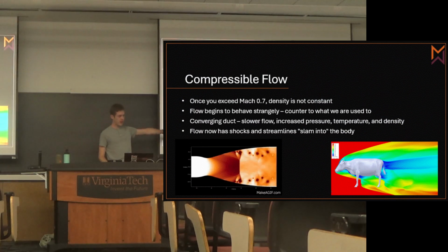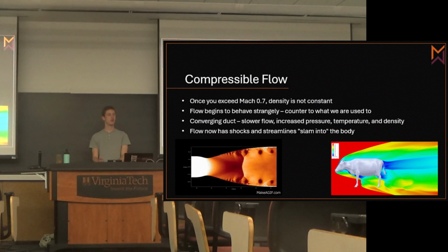And then I like to imagine when you go to compressible flow, especially once you go past Mach 1, that instead of a bunch of runners, you're a bunch of people on a highway with blindfolds trying to go as fast as they can. If someone stops ahead of you, you're not going to stop until you slam into the back of them, and that's the only way you're going to find out about it. How fast am I willing to go on a highway when I'm blindfolded? If I go down to 2 lanes with a bunch of people on it, you're going to go really slowly because you don't want to crash into anybody. But if I open it up to 20 lanes, then you feel more free to go as fast as you want, because the chance that you're going to hit somebody goes down. So that's a conceptual way of rationalizing why this is happening.